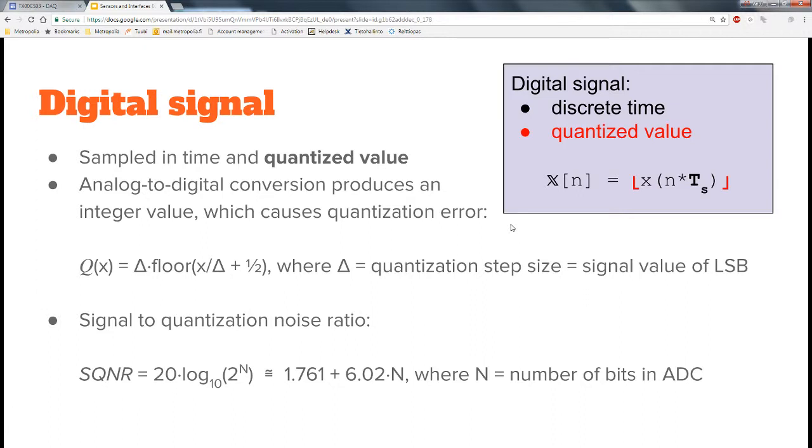So N would be something like 14, 15, no, 16 bits. Yeah, it gives about 100 dB. Oh, that would be 95. For 100 dB you need actually 17 bits. Yes. Okay, so how to select your A to D converter? Well, based on the required accuracy, or actually this is just the resolution, not accuracy, not precision, but resolution, simply given by the signal to noise ratio.